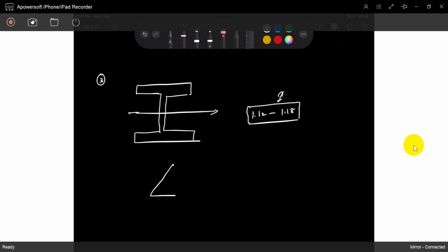And also if you see a triangular section, the shape factor is 2.34. Too much. 234%, not 50%. Double, more than double is there. If you do elastic analysis, the moment of resistance is 100. If you do the plastic analysis, 234 will come. So you will only design for 100, but it has a capacity of 234 at the ultimate. We wasted so much.